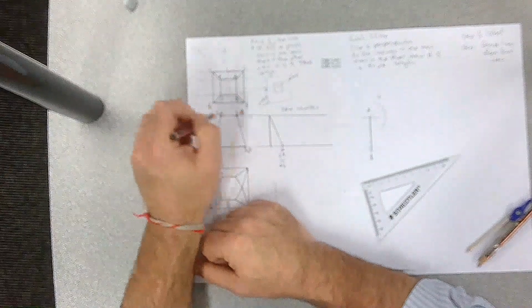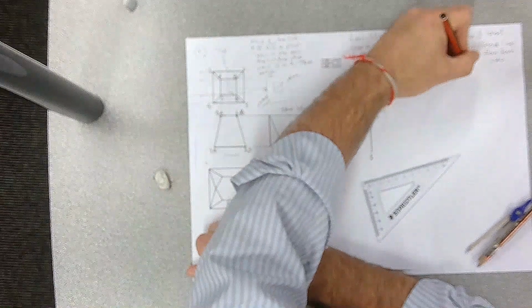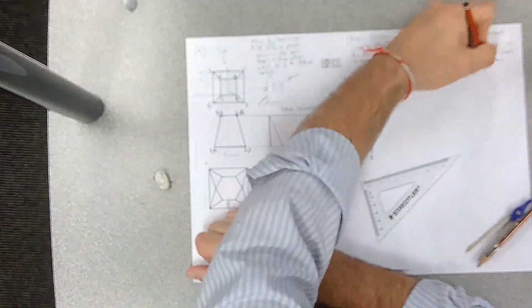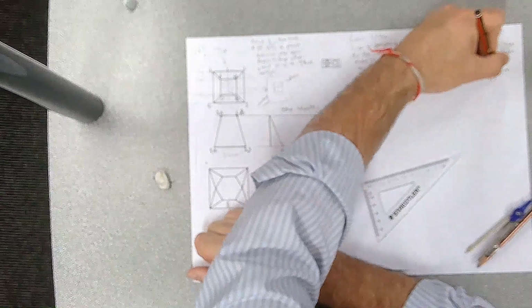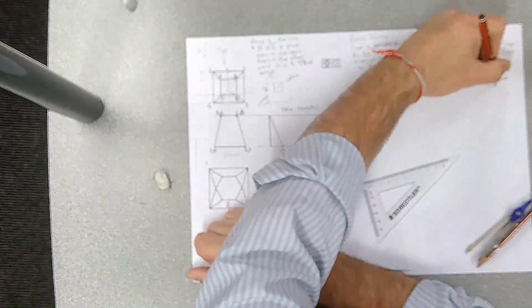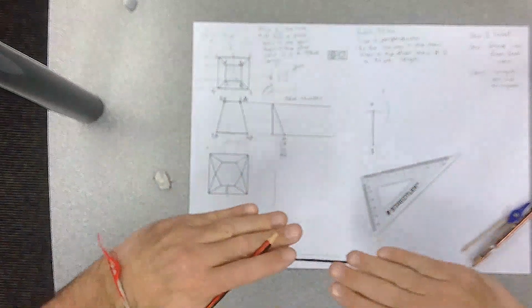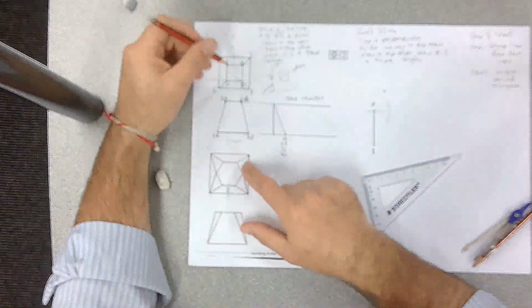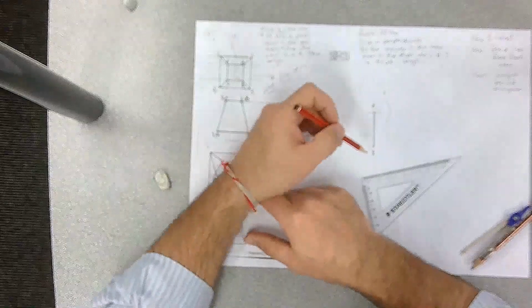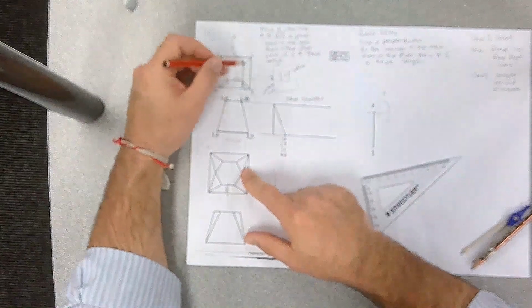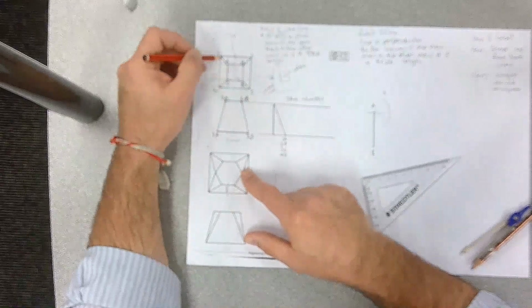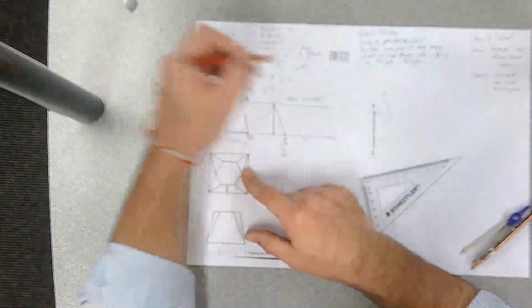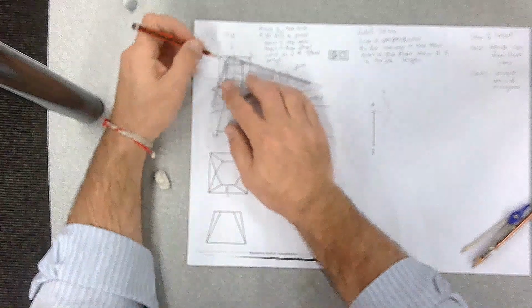So for this thing here, step 3 is really going to be about swing an arc and triangulate. And triangulation is any of these sides that are sloping away from a vertical or horizontal, you need to triangulate. So we need to find another point that goes from 1 to B. Okay, so we've gone A to B, and we need to find another point, and we've only got one other point we can use, and that's 1.